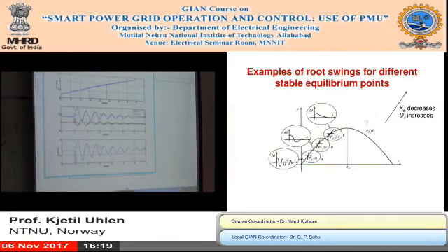The point is that you have the oscillations happening along the power versus angle curve, which is fairly linear in this range. So it's more or less valid to assume that this is a linear system, so we could apply the linear theory, and you get a damped oscillation.